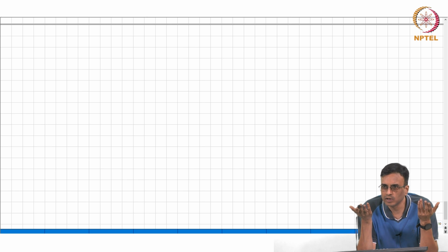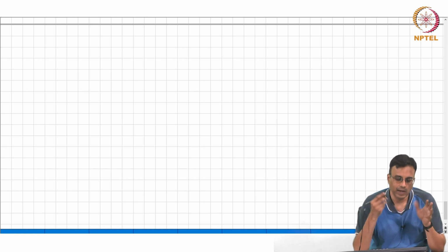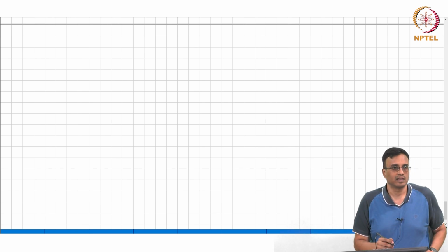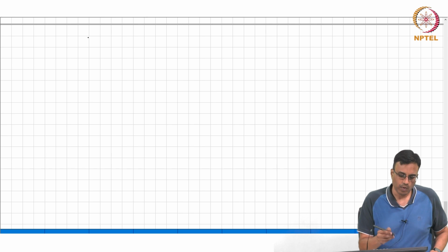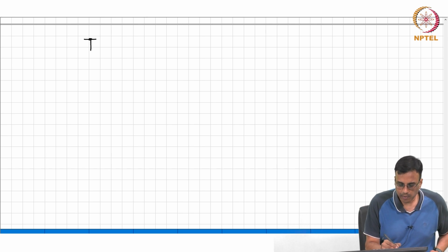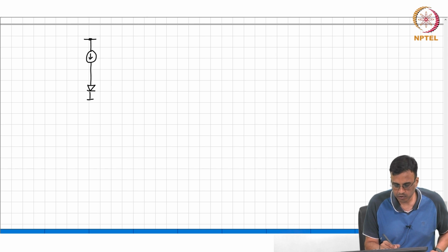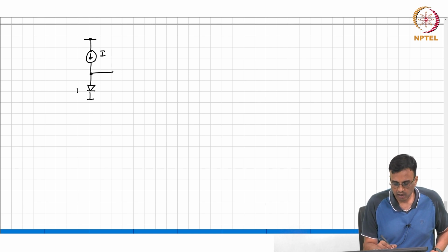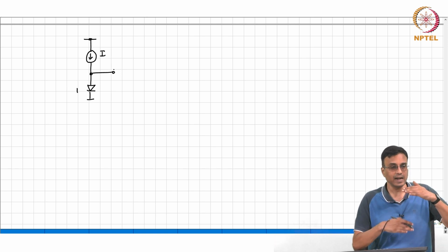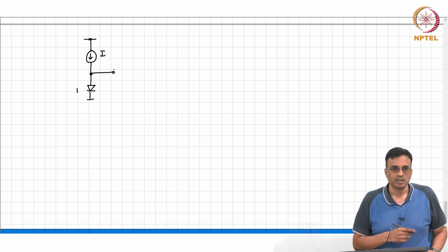Normal diode. And what about the normal diode? Yeah. So, in all our problems, we said the voltage drop across a forward biased diode is 0.7 volts. So that seems like a reasonable place to start. So you take a diode and then bias it, push some current through it, and to first order, we said that the voltage is about 0.65 to 0.7 volts.